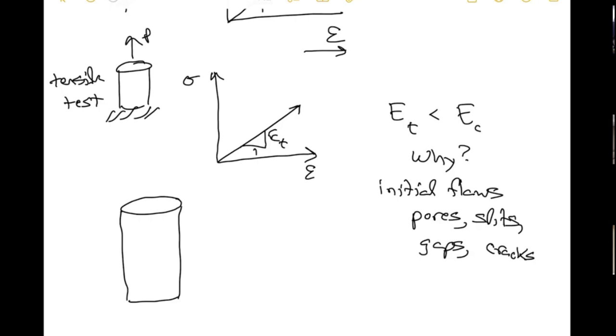And if you actually have, let's just exaggerate this, but you have this thing like that, and say you took a machine and you machined in three little gaps like that, and they're oriented in that direction. And so if you pull this, those surfaces are not participating in providing any stiffness if you pull it. And so you'll get a certain resistance, which the slope of that thing is going to be your modulus.